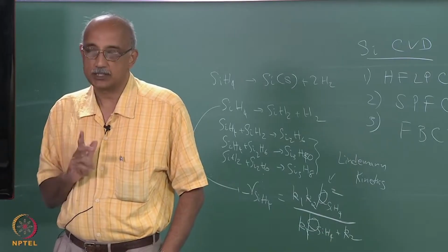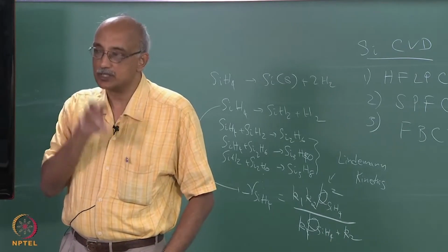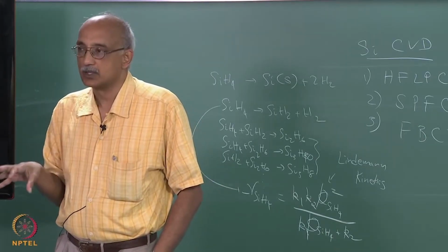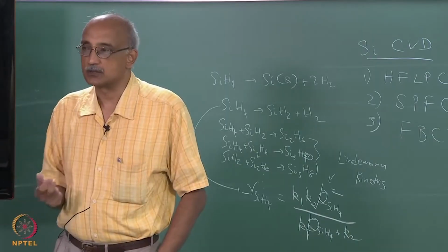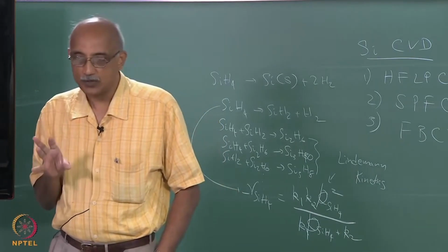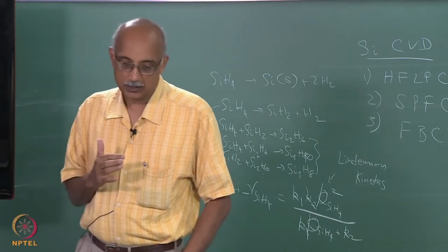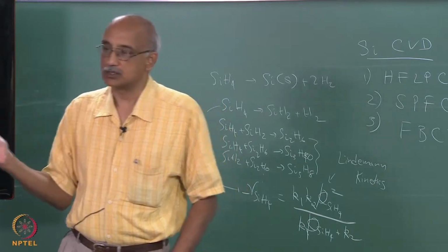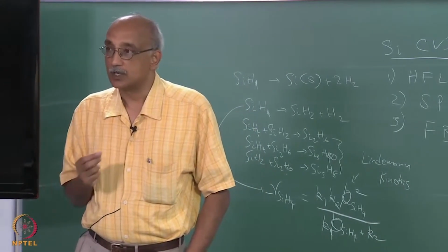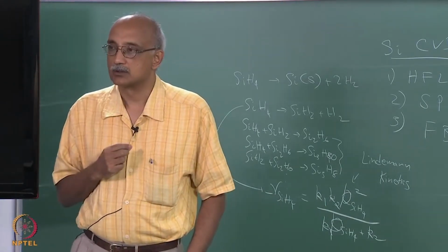The problem with it is, in terms of the rigor, there is always a difference between the first principles model and a UDF that is provided strictly based on experimental observations. There is always a question mark when you are providing a subroutine that is experimentally derived, because there is no guarantee that if you extend your experimental conditions, you will still get the same rate law. All of user defined function.